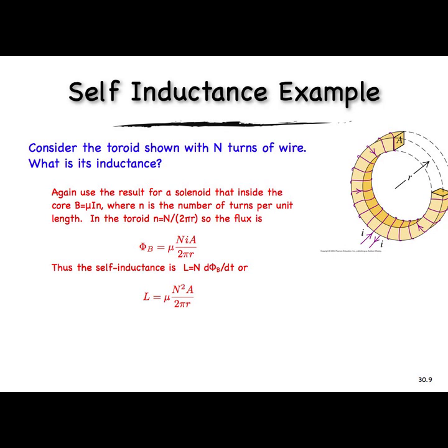So these devices that exhibit self-inductance can be useful in circuits. We call them inductors. They tend to look exactly like what you would expect based on the schematics and the diagrams we've been showing. They tend to look like coils of wire, usually wrapped around an iron core. And oftentimes that core is toroidal, so that the circulating field loops in around itself, and you don't get magnetic leakage that can induce interference in neighboring parts of the circuit.